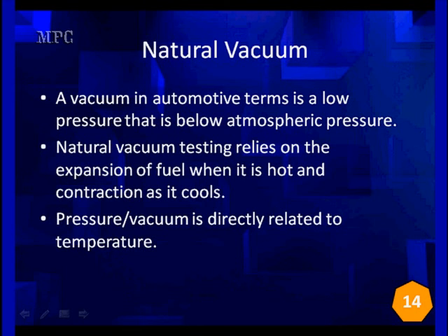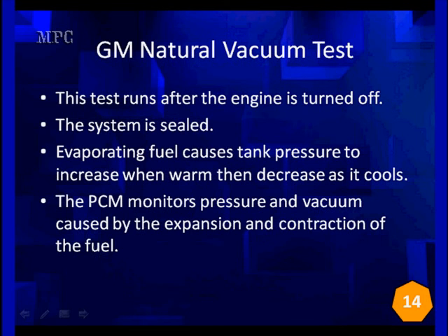The natural vacuum testing relies on the expansion of fuel when it's hot and the contraction as it cools. Pressure and vacuum are directly related to temperature. You heat up gas in a sealed container, it will expand and build pressure. Cool gas in a sealed container, it'll create a vacuum. And that's the technique we're going to use for natural vacuum. It's no more complicated than that.